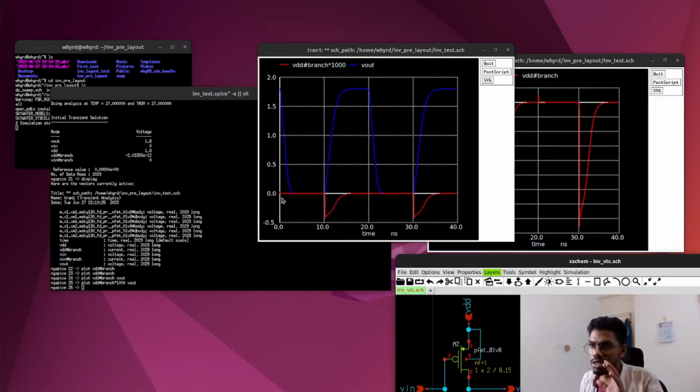But in today's power analysis, we will analyze the power together. All three components we will take together, right? And how? Because we will do the integration of our current. Any current we are drawing in any phase of the operation is dynamic, but this is also short circuit power in some terms. Because short circuit power comes only due to non-ideality of our input clock, right?